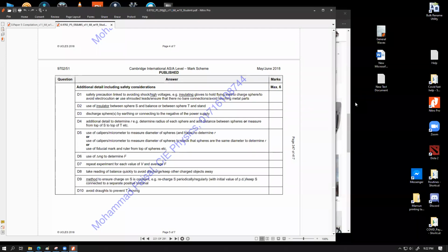One of these examples is a pretty nice one: in cases where you are about to use a voltmeter, you can always connect a CRO and measure the voltage from the CRO by multiplying the Y gain by the Y-axis division. These are usually 2 extra steps if you're using a CRO in place of a voltmeter. They can be used interchangeably, but using a CRO can give you at least one additional detail which is relevant for the CRO, but not for the voltmeter.